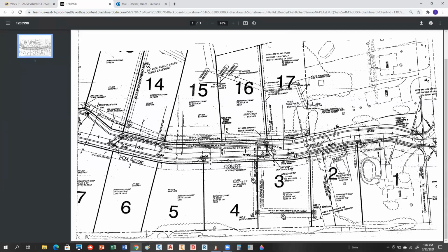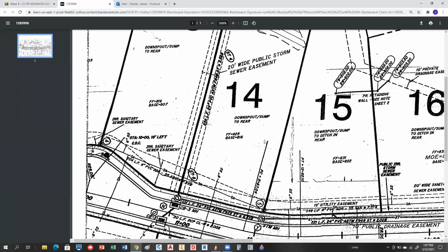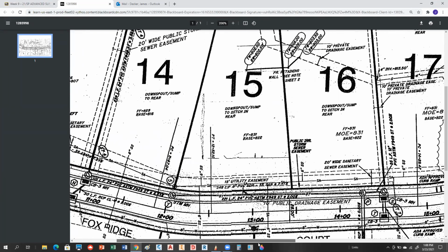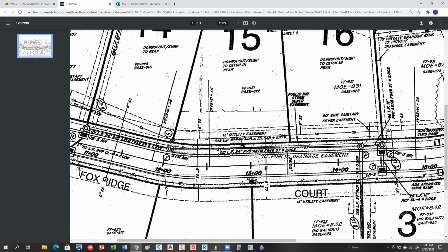On the plan sheet, what you're going to see is things like the manhole locations. Typically, it'll tell you things like the distance in linear feet, the diameter, and the slope. Those are going to be critical features. And what we'll be doing, if we get a chance to do this on Thursday, is setting up a sewer, staking the manhole, staking an offset, and putting control stakes along that sewer at a certain interval.